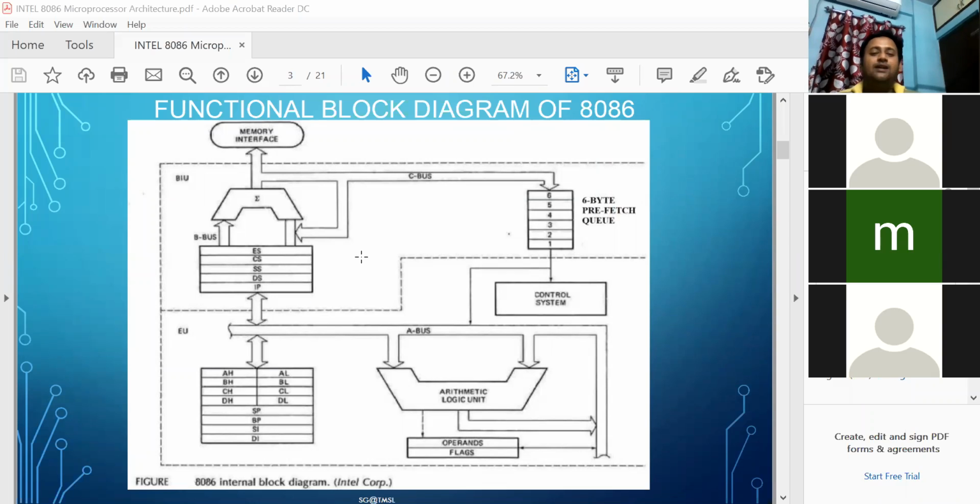One difference between the 8085 and 8086 is that in 8085 all the operations are accumulator oriented. By default, the accumulator operates on one data byte, and the result is stored automatically inside the accumulator. But in 8086, you can add any register to any register, and the result will be stored according to your requirement. Any register can be used to store the result. So if it is written as ADD BL, CL, after addition the result will be stored inside BL.